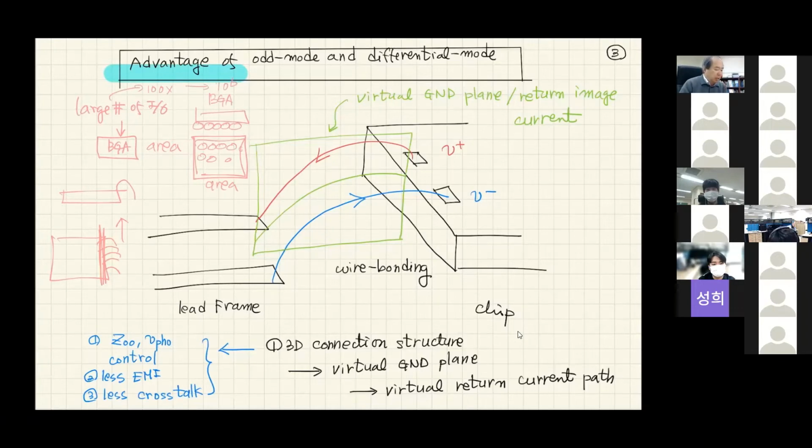So we cannot use this wire bond type anymore, but still some high-speed interconnections such as optical fiber communication drivers and receivers are still using wire bonding. And in the single-ended wire bonding case, if this is a wire and this is a ground, there is such a high distance from wire to ground that this becomes very high impedance, and this will cause reflections.